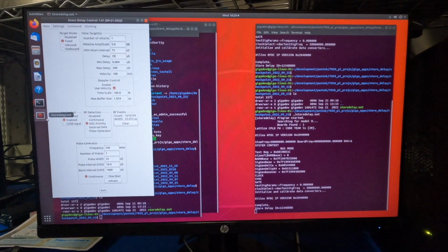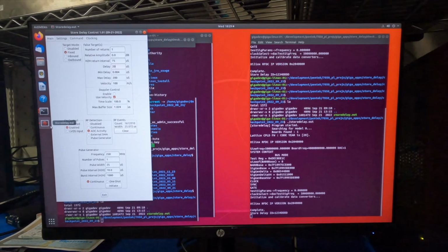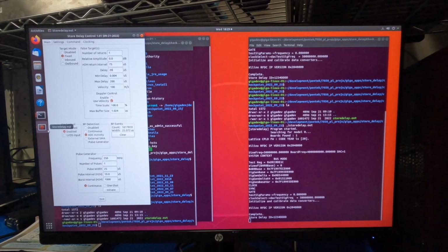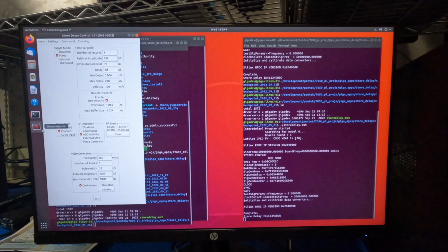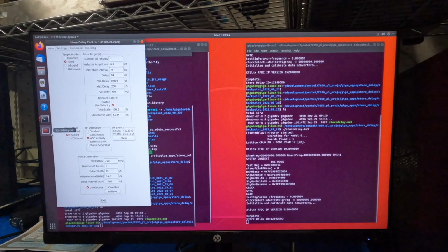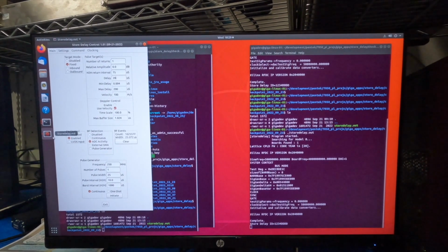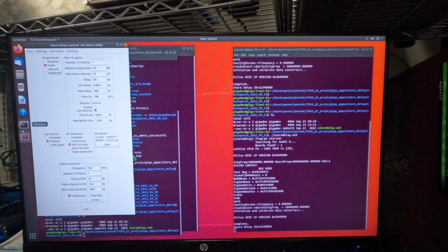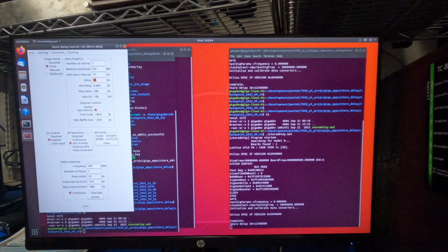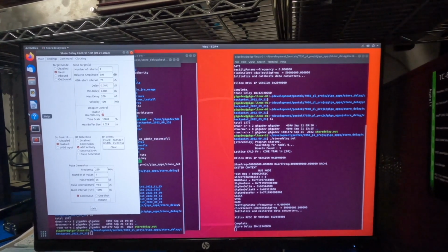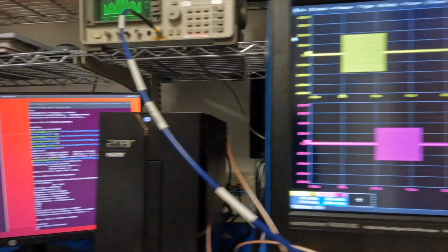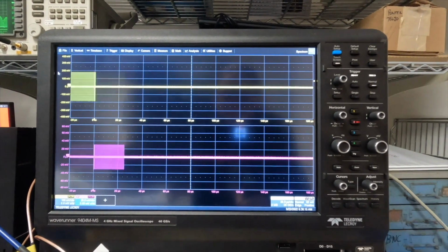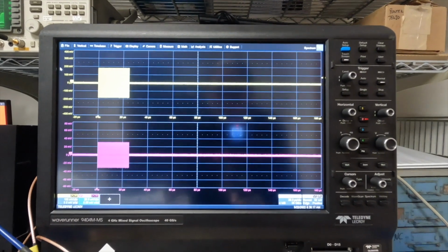Okay, so the first DRFM mode we're going to show you is multiple range false targets, with and without Doppler. And the first thing we want to show you is the control for the delay from when the energy is sampled to when the energy is retransmitted. So for right now, we have a start of 20 microseconds, and we're going to shift that to the absolute minimum delay of just 4 nanoseconds. So that's the minimum delay mode, and you would normally start there